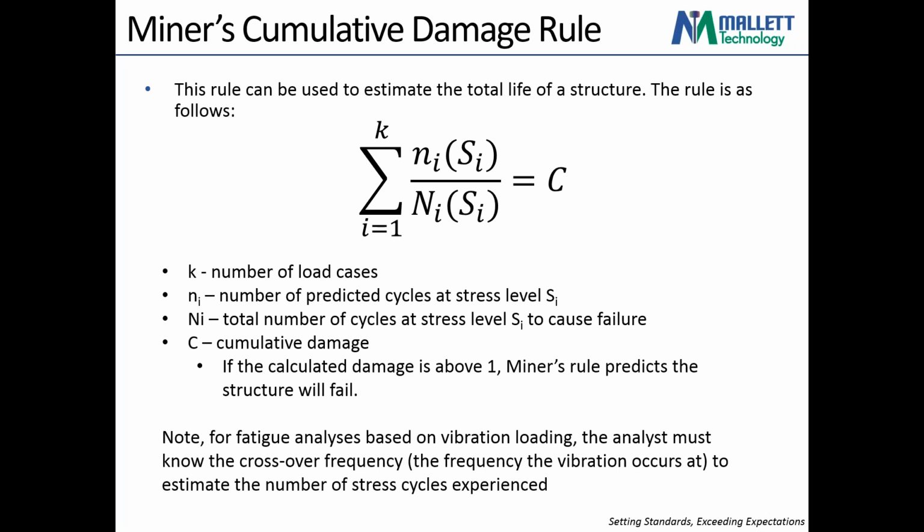get factors for each load case and you sum them together. If that cumulative damage is below 1, then my structure is safe. If it's above 1, it's going to fail, right?